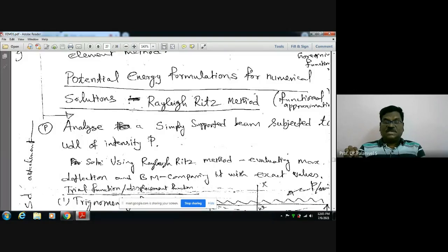Now, what I want to say: when a body is subject to loads, it deforms. Does it keep on deforming? No, it deforms, then it comes to rest, it is stationary. By extremum, it means the total potential energy has attained an extremum value, a stationary value. How do you get a quantity to attain an extremum or stationary value? Its variation must be zero. In other words, its derivative must be zero. Variation means derivative, differentiation. The first derivative must be zero.